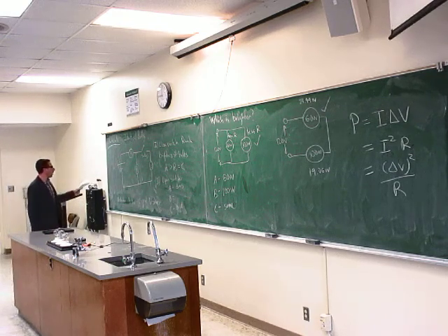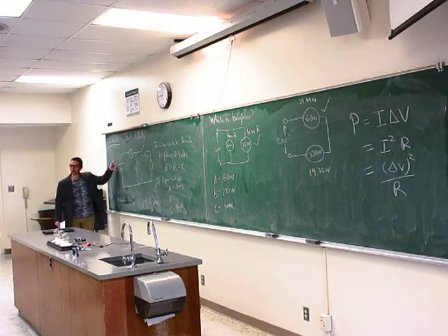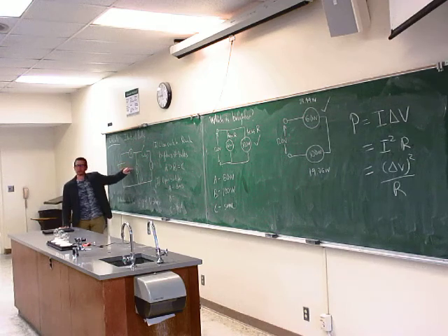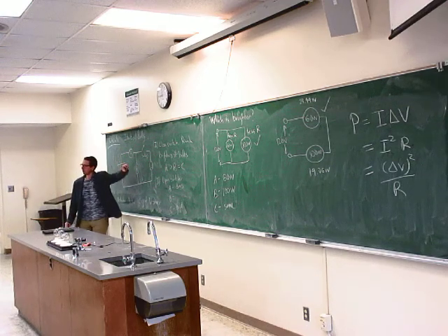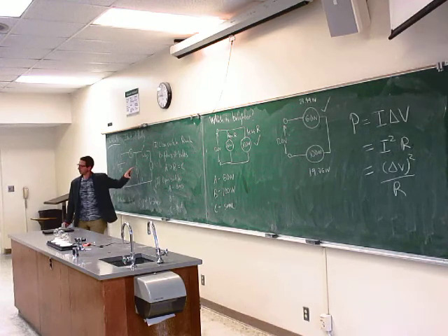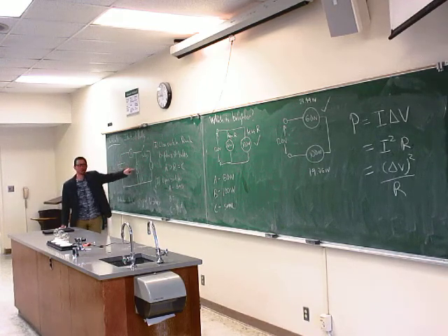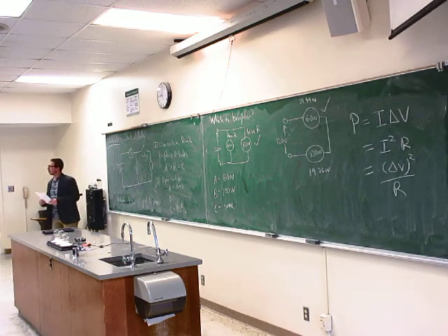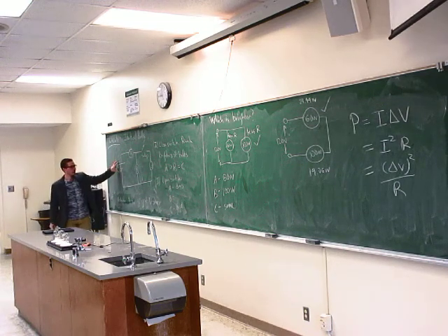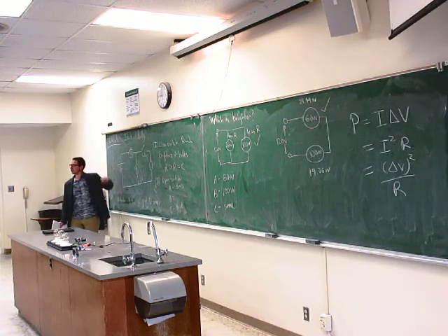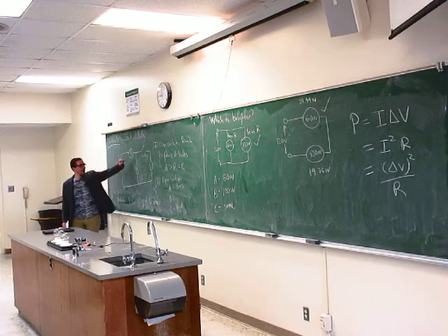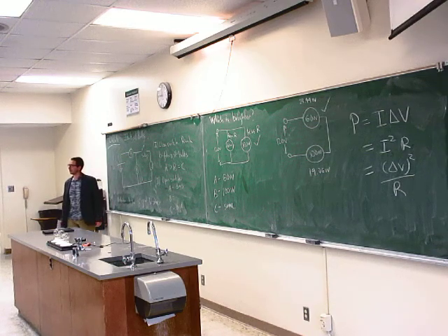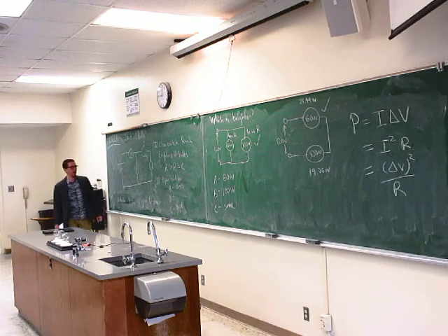Right? So now the effective resistance, or the load resistance across the battery, is not 1 R plus 2 R's in parallel. 2 R's in parallel is half the resistance. Now it's R plus R, 2R. So you have more resistance. The battery feels a larger resistance. So there's less current now going through bulb A. It has the same resistance, so it's not burning quite as brightly as it was before.